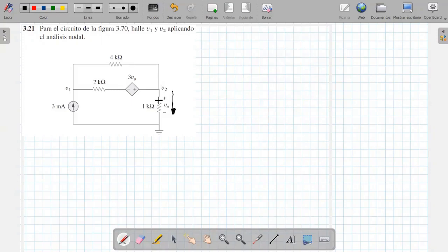In this way the current comes through this resistance. Already having this current, we can guide ourselves to mark the others. For example, the current from the independent source of 3 milliamps between this point and here has to go the other way. What occurs to me is that it is divided into two parts. One part comes this way and the other part comes this way. Here it comes this way, and it comes to this point and joins again, and they go down this side.